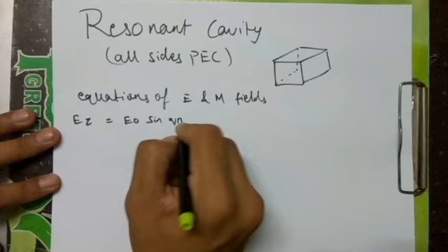Let's now cover the space with PEC from all the sides. We get a cube called a resonant cavity. A resonant cavity is a special type of resonator consisting of a closed metal structure that confines electromagnetic fields. The structure is either hollow or filled with dielectric material. The EM waves bounce back and forth between the walls of the cavity. At the cavity's resonant frequencies, they reinforce to form standing waves in the cavity. Therefore, the cavity functions similarly to an organ pipe or sound box in a musical instrument, oscillating preferentially at a series of frequencies, its resonant frequencies.